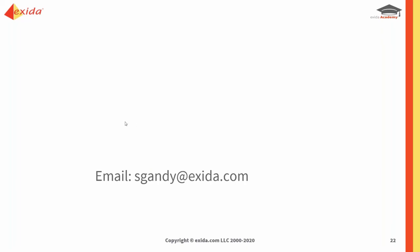So this safety manual will tell you when you have to replace and refurbish. The proof test interval is usually a function of end user practices. That's why you shouldn't design in isolation. I had one client where the engineering company, in order to meet the SIL target for the SIF, used a 3 months proof test interval. And of course, the end user said, well, that's impossible. We can't do 3 months. So they were already set up to fail. So that's why it's important to make sure you understand the practices of the end user, the site, talk to the maintenance people, find out what their sore thumbs are. Don't put in proof test intervals that are not realistic and will never be achieved.